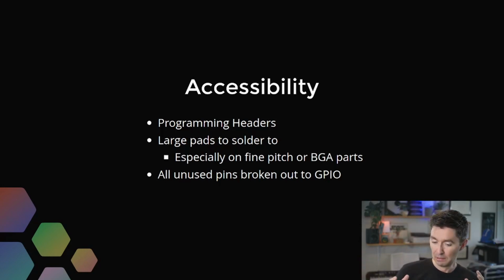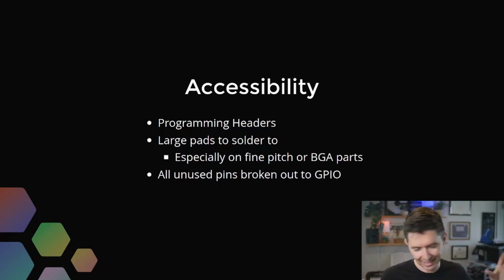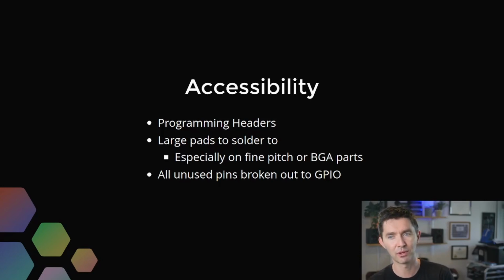Again, this is built on the idea that you have a lot of space in your board, and if your hardware engineer says, I can't fit this stuff because we're trying to fit this inside this tiny little case, if that's not a true requirement, I'd say ask them, can we go bigger? Can we have this very, very large accessible board so we can try all these different things we're trying to do? And Rev B can be that shrunk down version. So that's an important thing there.